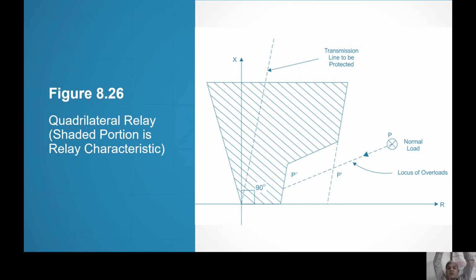I don't mean to say that you should allow a transmission line to take high overload. Power is flowing from station A to station B. Overload is occurring. The person at station B will come to know that overload has occurred, so he will take necessary action to shed the load and bring the load back to normal.